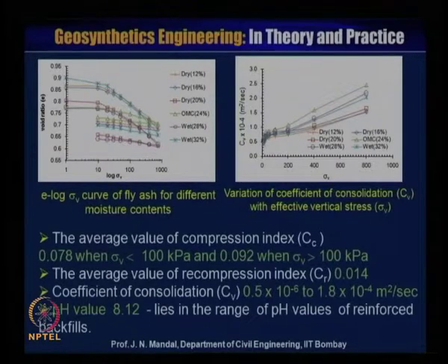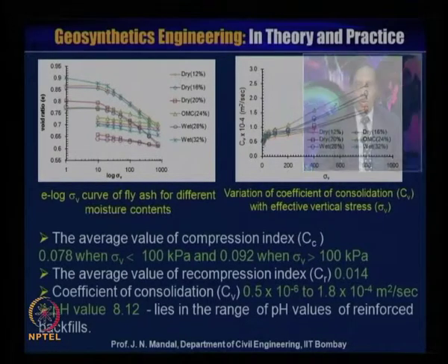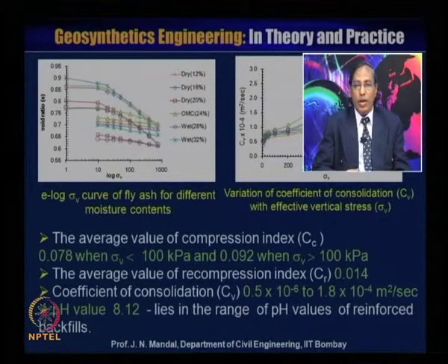The average value of recompression index Cr is 0.014. The coefficient of consolidation also lies between 0.5 × 10^-6 to 1.8 × 10^-4 meter square per second.